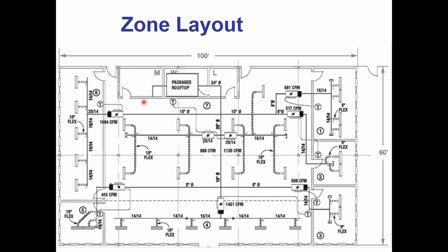The other thing I'll point out on this drawing is that some of these dampers have a little black box on the end of them. And then the 2 in the middle don't have a black box. For this particular drawing, that little black box meant a supplemental duct heater. In our climate here in the Midwest, even though I have a building that's cooling dominated, and even though my air handler is going to run cooling all the time, my perimeter zones that have all this glass window exposure, those guys are going to need heat at some points of the year.